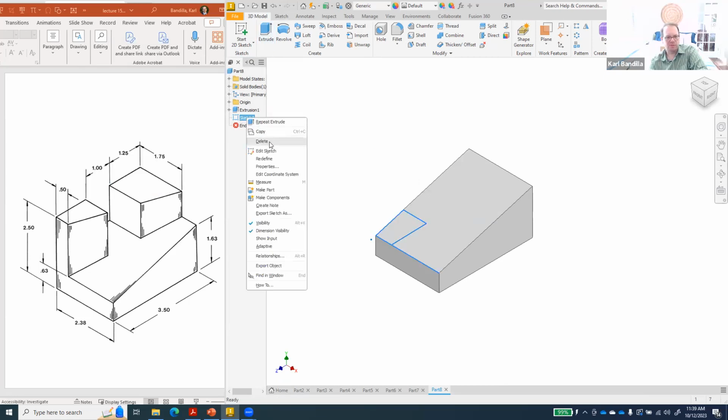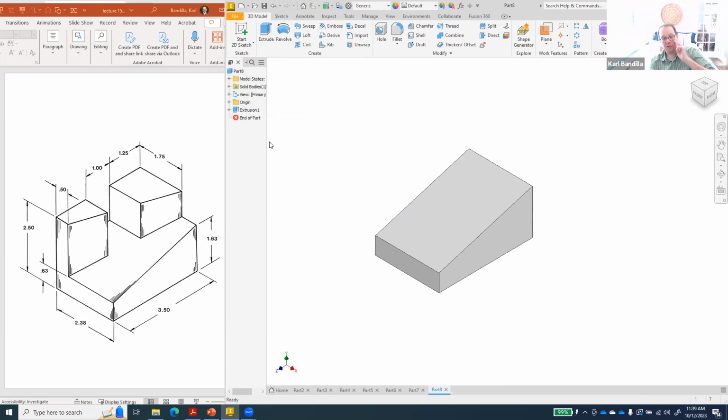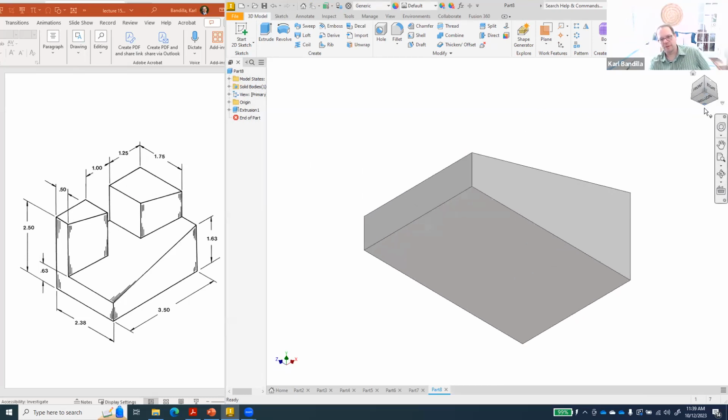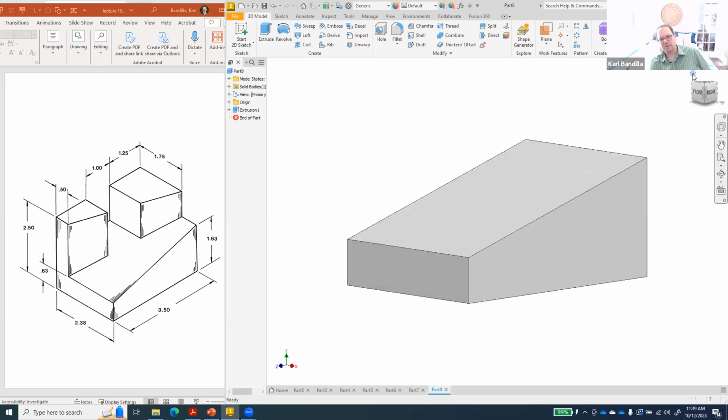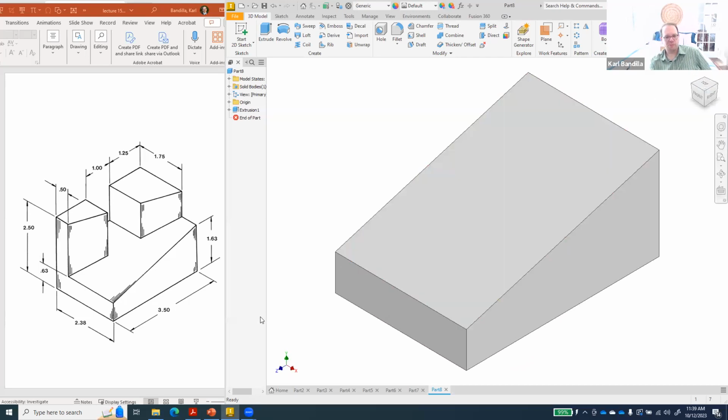So let's get rid of this one. So there's a couple different ways we could do this. We could just flip this over and draw on the bottom, which is flat. That's a little annoying because it's a little hard to see. And we want to practice our work planes a little bit. So what I suggest we do is we basically create a plane that's up here at the top end of our little extra blocks, and then we can extrude downward. And that's really easy.